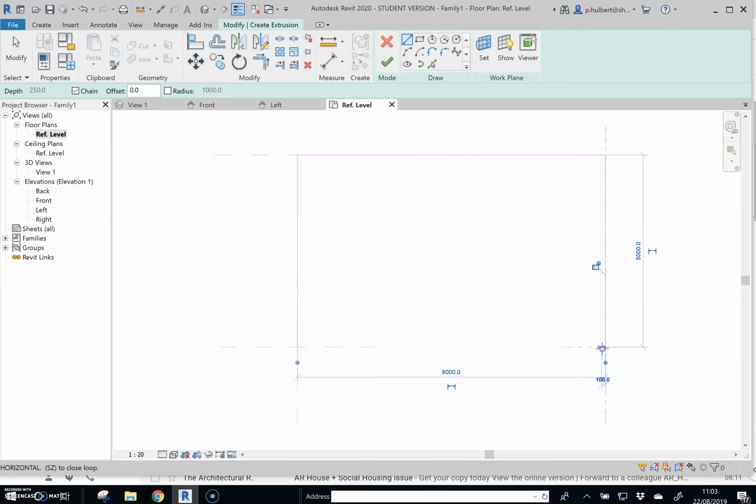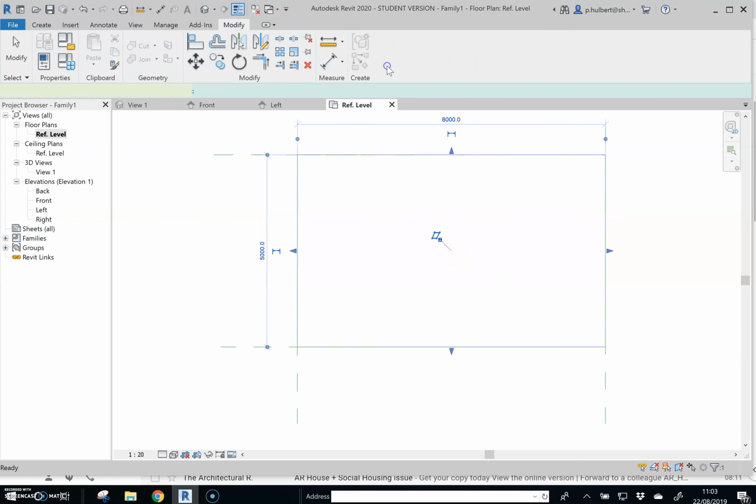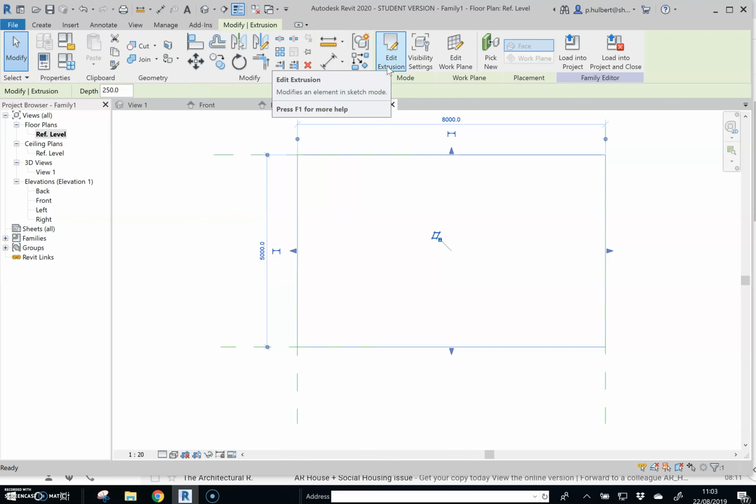So you get to that point, 5, and then back to here. So you've now created this purple line, which is your extrusion. You have to press the green button to say I've finished and I'm complete. If you start moving on different menus now, things go wrong and it doesn't like it, so you must press the green button. So now you've said I've created a rectangle.